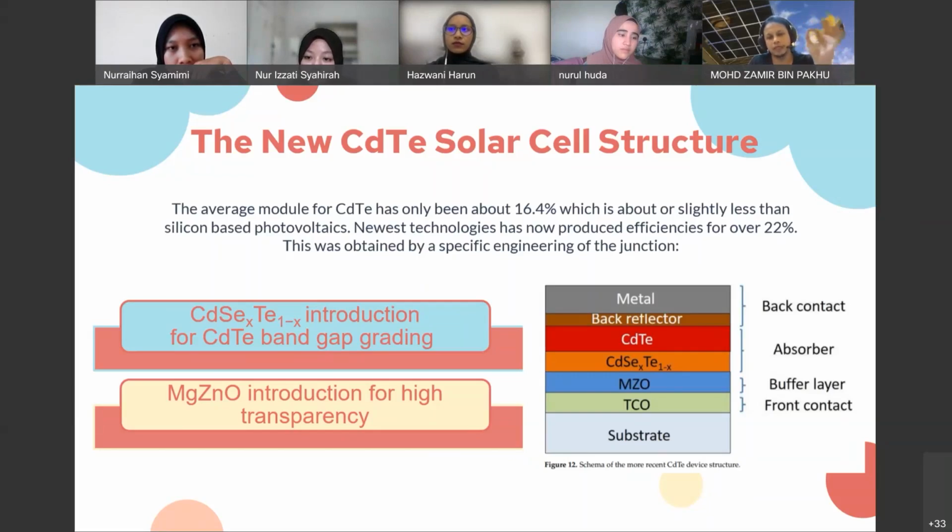Okay, so the key concern with this technology is the cadmium, but it's doing the job very well. It's doing the job well at light conversion and stuff, but it's toxic to begin with. All right, so therefore the program has to be properly in place. I think if you do some reading for the window material, the key is to have good band alignment with cadmium telluride, and the window layer has similar band gaps of about 2.3, 2.4 eV like cadmium sulfide.